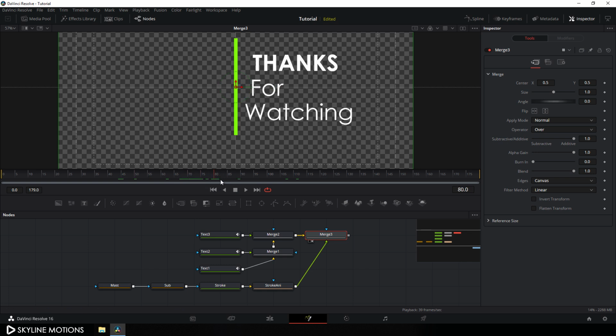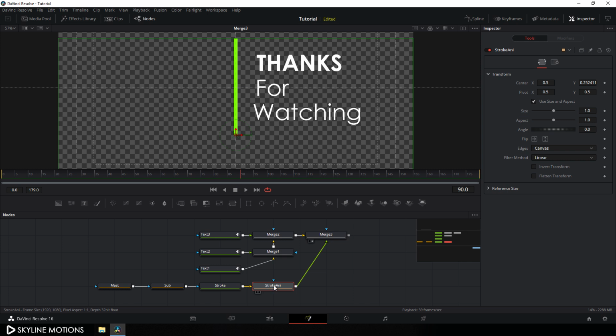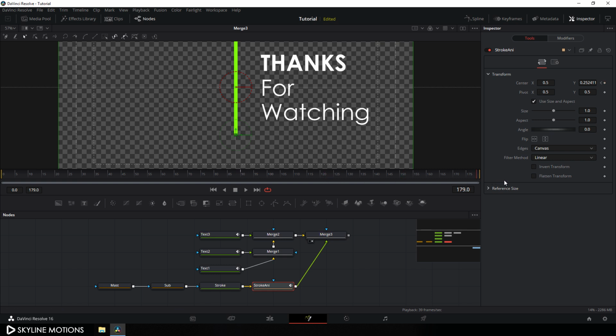So just go to the center of this timeline on frame number 90, which is equal to 1.5 seconds. Select this stroke animation and here we have center X. So right click on center X, click on animate and go to the end of this animation and just drag this line right over here on the right hand side and set this value in round figure 1.